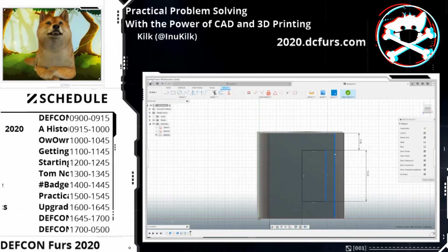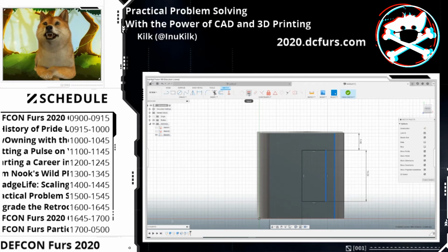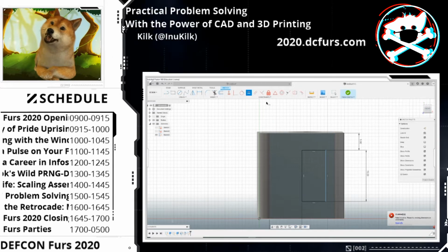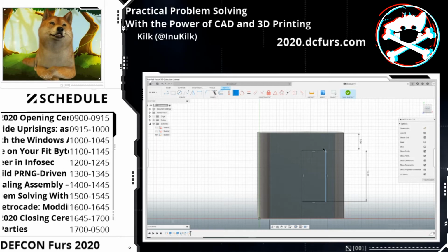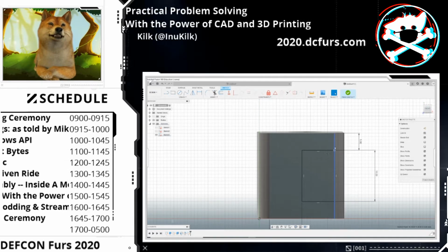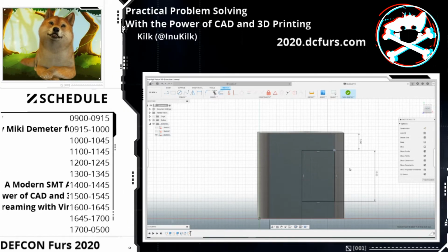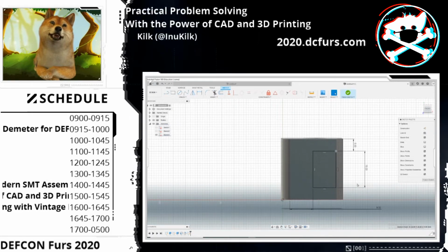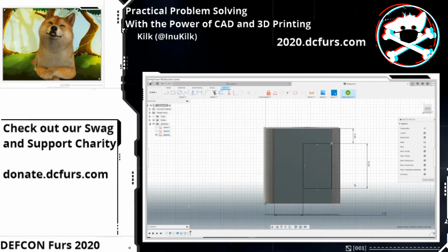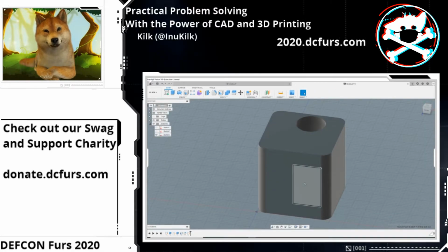What we can do here is hit these 2 lines, and let's add a constraint called equal. That didn't work. Let's add coincident or coincide. Yeah, you know what I mean. Basically, you click that point, you click the line, and so this point here will coincide with this, and so that means you can't move it now because it's coinciding with that line. It'll always meet at that point. So let's finish the sketch here. So we've just created another sketch here.